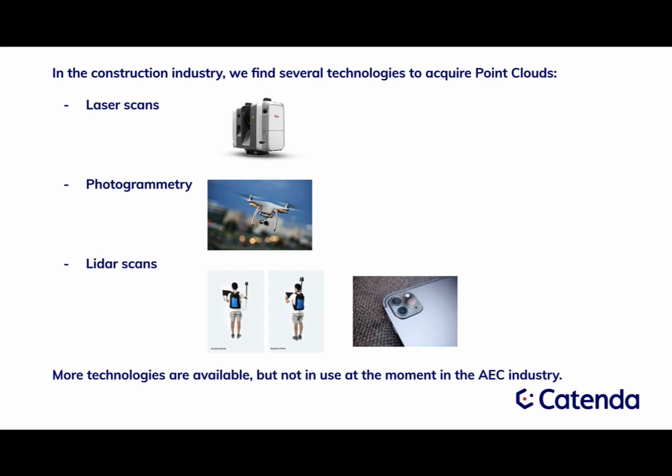Most of the time, it's done by surveyors. So you need to order your surveyors to do a scan, and some of them already do it by default nowadays. You have several technologies available on the market for the construction industry, the first one being laser scanning. There are brands providing devices, like Leica, for instance, and you basically fire a laser beam at the surroundings where you place the laser scanner, and you collect at every point the XYZ coordinates and some other data that you save as a file.